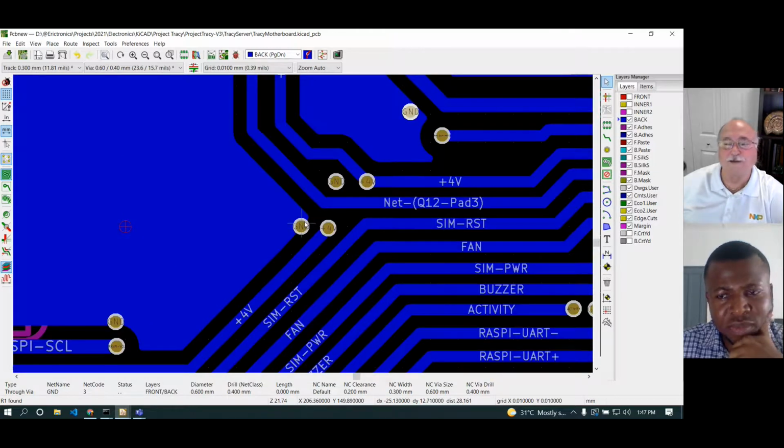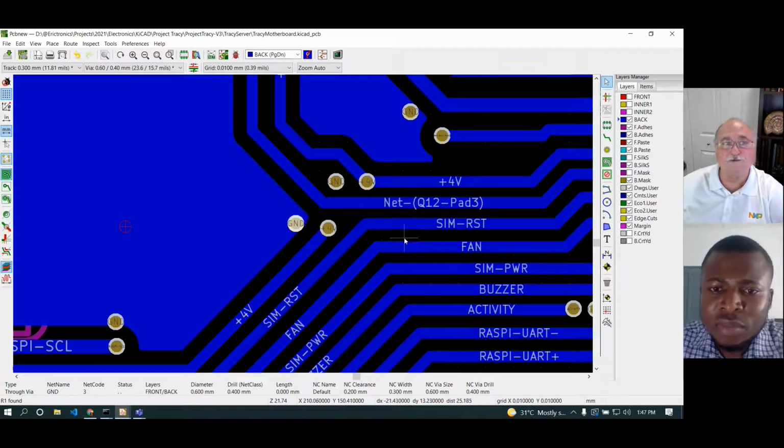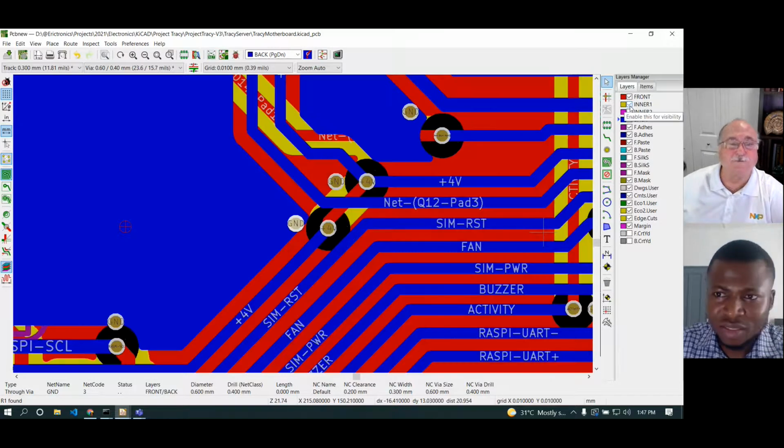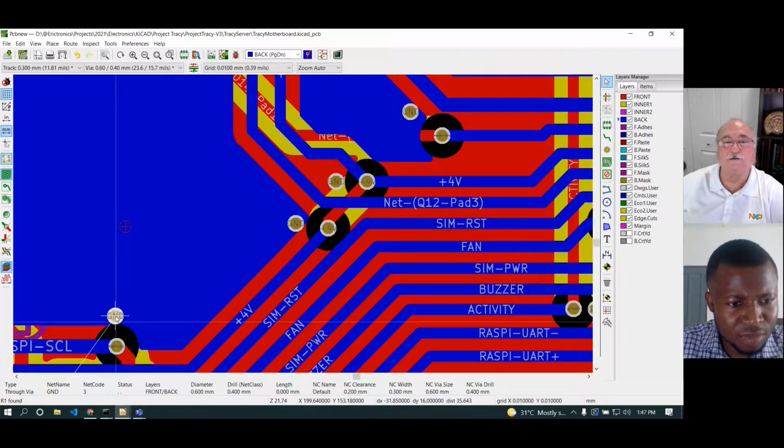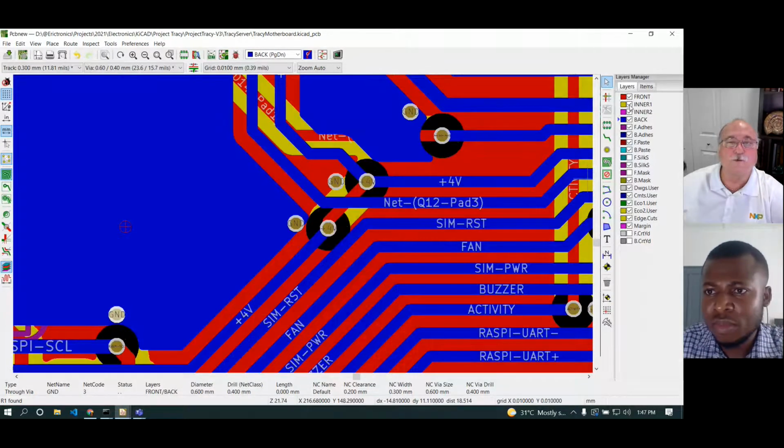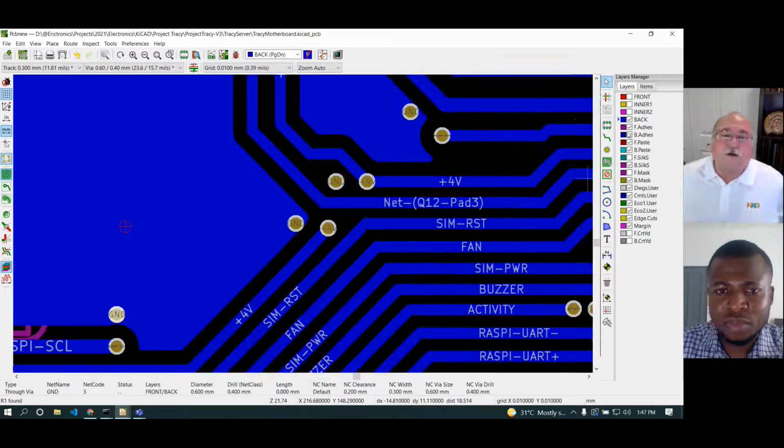This is the reason I focus on this: I have seen many times where a single missing ground transition via has caused EMC failures, and even sometimes functional issues, because that discontinuity caused by not having a close ground via would induce a signal integrity problem.